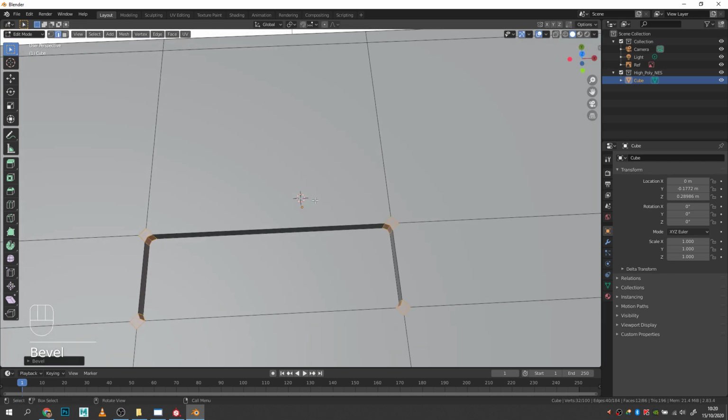Cool. Then 1 on the keyboard, I'm going to rejoin up these edges here because at the moment this shape is more than 4 sides, which is something we don't want. So select 1, hold down Shift, select the one that you want to join to, press J, and work your way around. J, J, and finally. Cool. So now we've got that curve that we want in here.